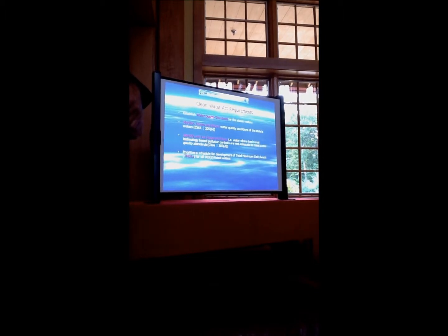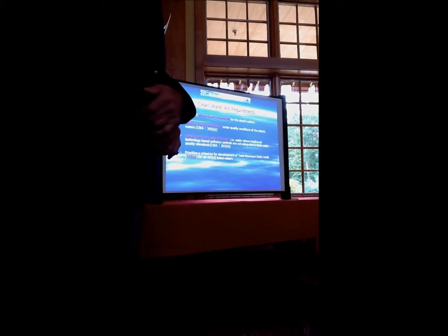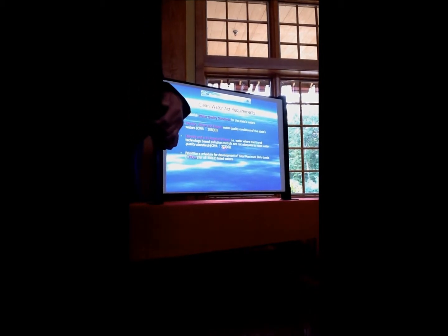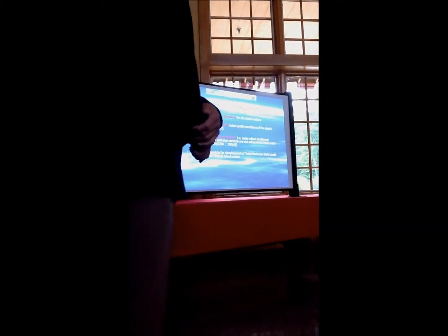Next, please. Okay, Clean Water Act. The biggest thing is establish water quality standards. Monitor and assess and report. Identify, list impaired waters. We do that every 2 years. It comes out with a list of impaired waters, our 303D list. We just had one released for 2012. It was approved by EPA. And then prioritize a schedule for developing total maximum daily loads. That's what the TMDL stands for.